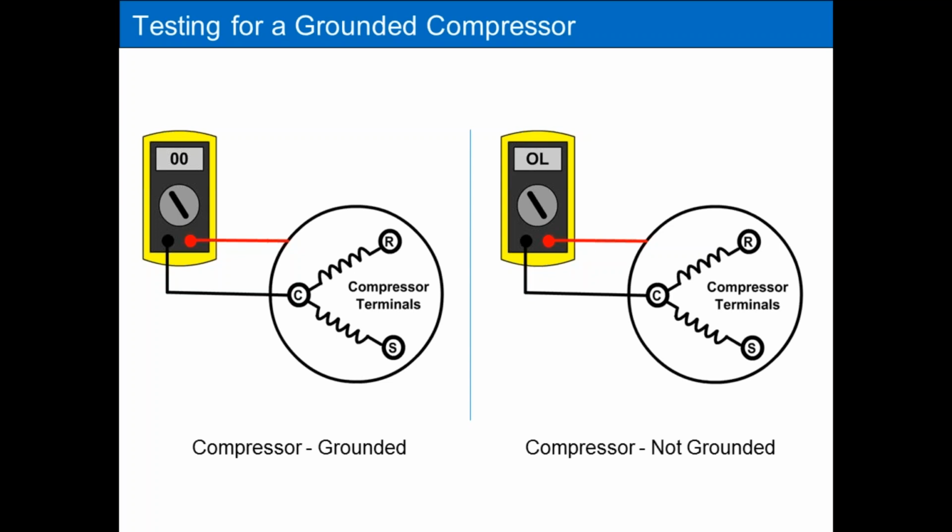from any terminal to ground using your standard ohmmeter that's not reading millions of ohms. Get away from the million ohm meters, because you may read millions of ohms from a terminal to ground. That doesn't mean it's shorted. It's just a high resistance value. So get away from these million ohm meters when you're doing these tests. They really can cause you some grief.